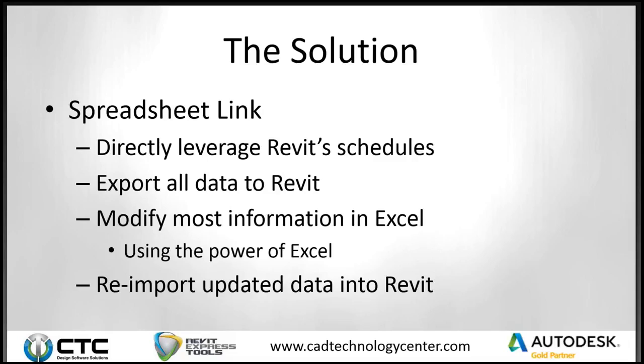The nice thing about Spreadsheet Link that we're going to work with today is it can directly leverage your Revit schedules. So whatever you have in your Revit schedule, you can directly push out to Excel and let them use. It can be more of an automated export even, if you want it to be. So it makes it really quick and easy. You can export all the data from Revit out. Then after you've modified that information in Excel using the power of Excel and some of its autofill workflows, you can re-import that information back into Revit.